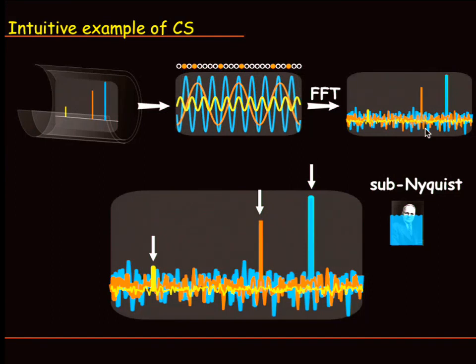It's what's called a point spread function. You take one peak, compute an inverse Fourier transform, and multiply by some mask, which is like filtering in the frequency domain. So it's a convolution with the inverse Fourier transform of the sampling pattern. So you're going to see some of these elements above that interference, and some that are small are going to be buried in it.